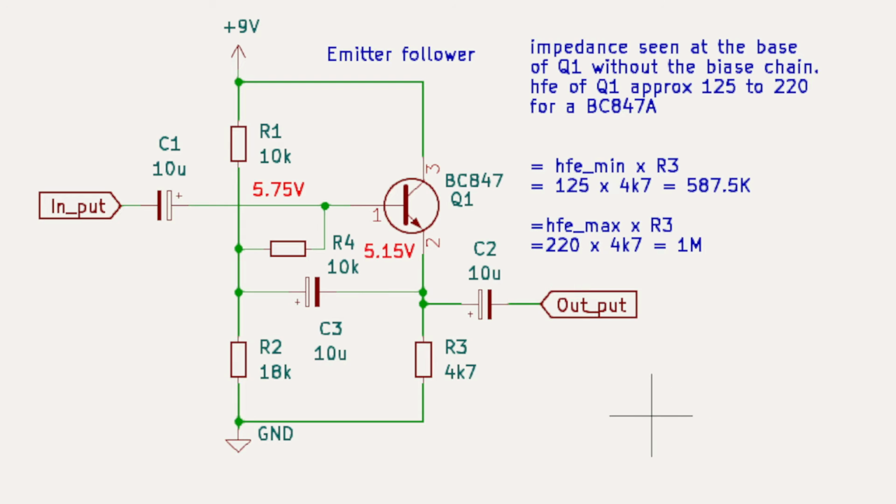But of course you've also got to take into account that the voltage at this point and the voltage at that point are not identical. The transistor does not provide 1-to-1 gain. It is less than 1. So there's going to be an imbalance in here. So there will be some current flowing through here, which of course means that some of this circuit, the bias, will be seen by the input.